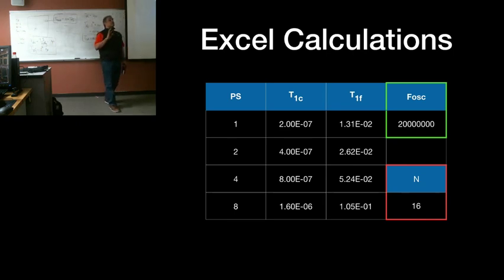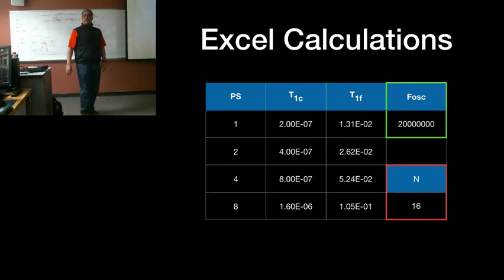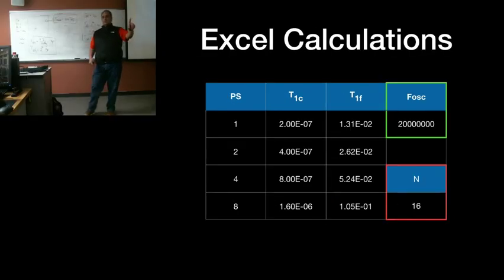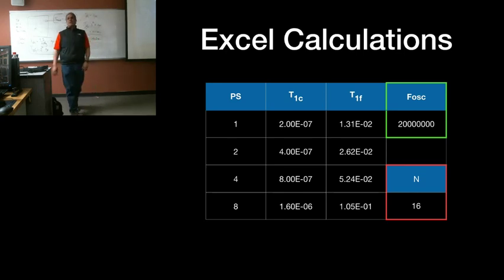I just want you to redo this work on your own. Just put it on an Excel spreadsheet and do it. Why? Because once you start doing quizzes on it, it allows you to have a frame of reference, right? If I ask you to create a 52.4 millisecond overflow, you can actually set it up for 20 megahertz at a prescale of 4 on a timer 1. You can do it. If I ask you to go in between, you can't do it. It cannot be done. I mean, it could be done, but not now. We'll show you how to mess around with the timer later.